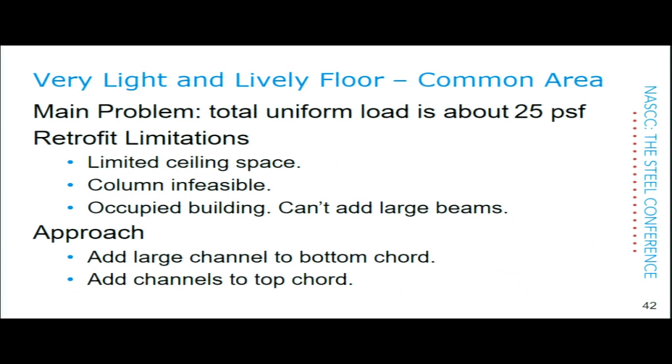Okay, so what's our problem here? We need to figure out what we are going to try to do to the structure to bring the vibration down. Well, the main problem was it just has no mass. Even with the superimposed mass, we have something like 25 psf, which is almost nothing, right? It's way low. It's like 3 times lower than what we would expect.